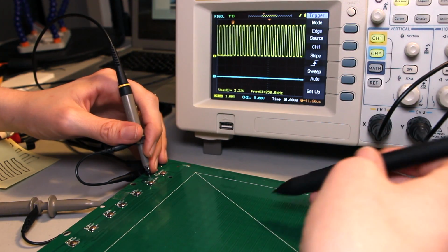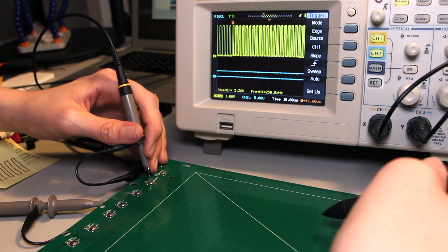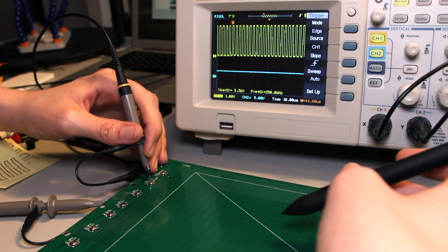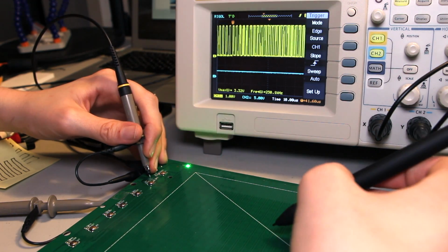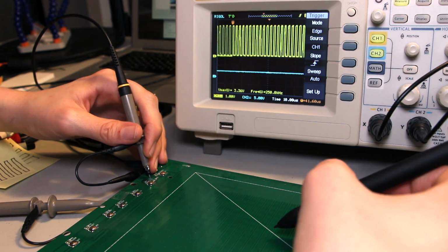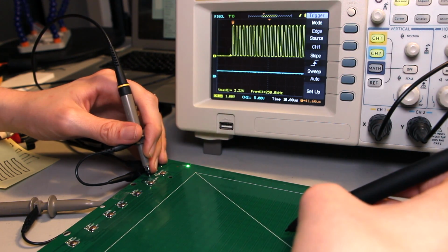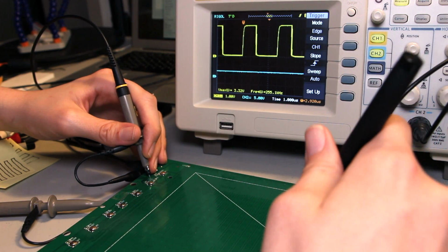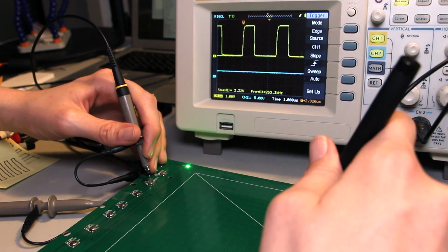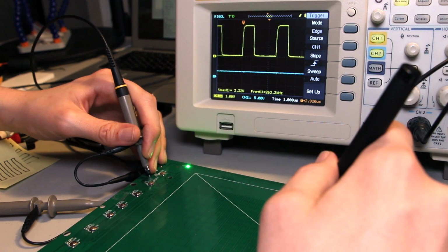The most straightforward signal we have coming out of the analog front end is a very heavily amplified version of the signal from the selected coil. This isn't really useful for determining the location of the pen, but this is a great way of measuring the frequency. The signal is a bit noisy and the duty cycle isn't 50%, but the frequency tracks pretty accurately with